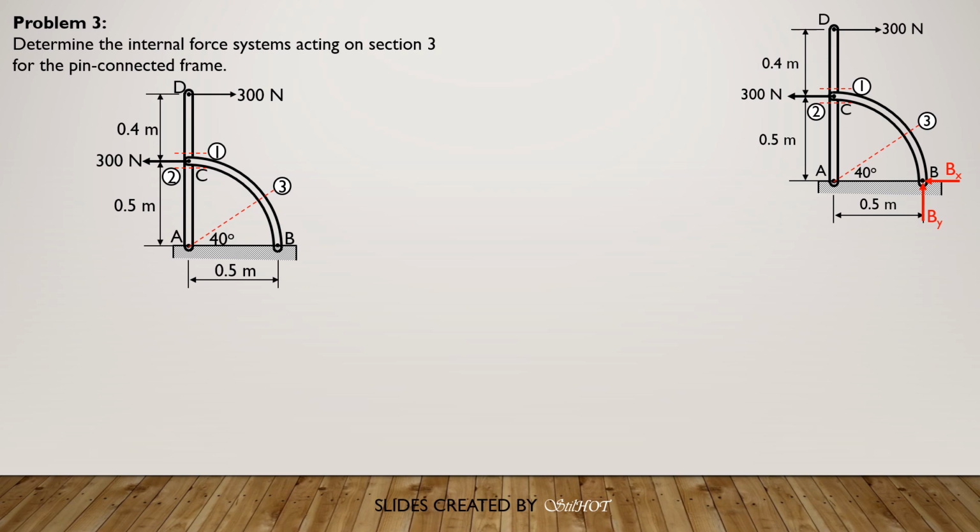horizontal, because this is 0.5 and 0.5, we conclude that BY and BX are equal, and the force is directed along an axis which makes 45 degrees with the horizontal or with the vertical, so the component reactions are equal. The magnitudes are equal. So summation of moment about A equals 0 considering the whole system. Counterclockwise positive, so BY times 0.5.